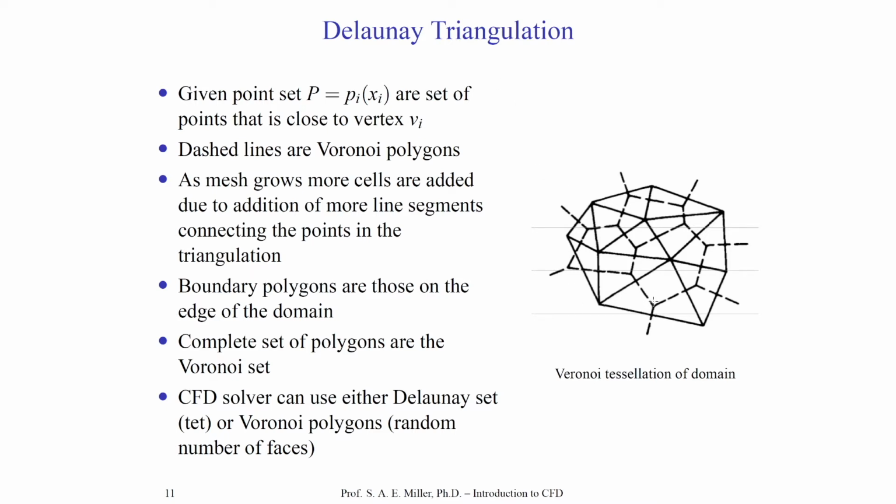Simply place grid points in between each triangle, and then move them to locations where the connectivity between each new grid point and each triangle becomes normal to the connectivity between the original Delaunay triangulation. You can see how this might be done, and the Voronoi polygons can then be seen as overlaid on the Delaunay triangulation. You can also do this in 3 dimensions, except the connectivity between the Voronoi polygons will be going through faces of the triangles of the tetrahedrals in the Delaunay tetrahedral mesh.